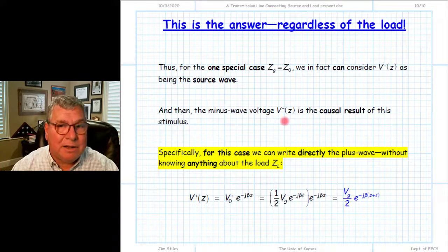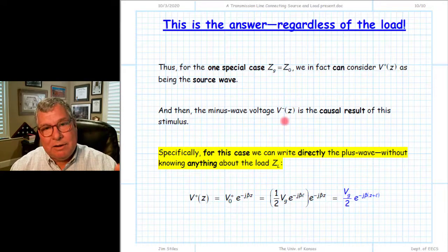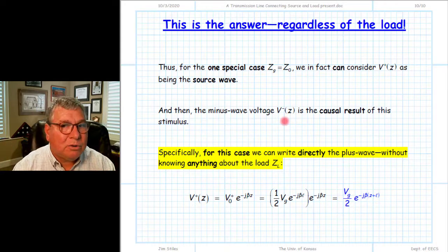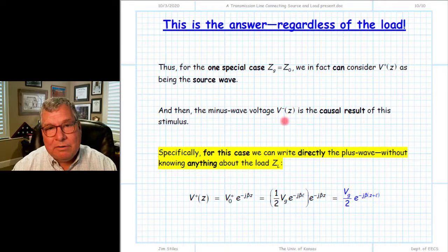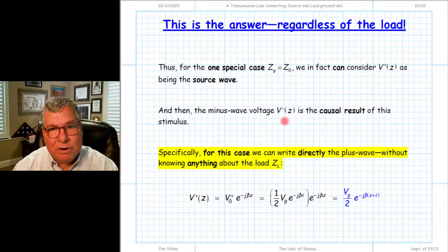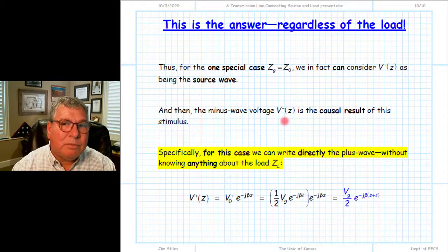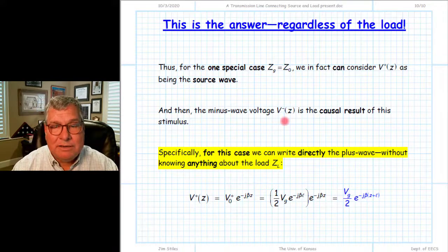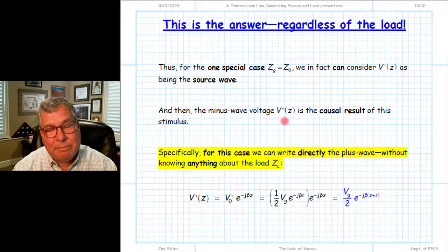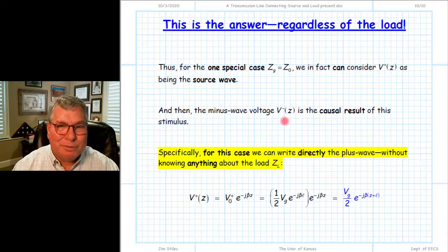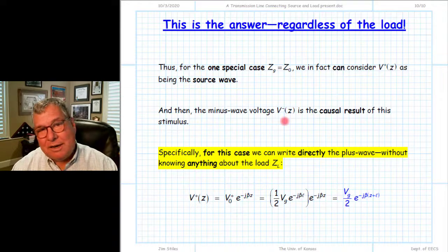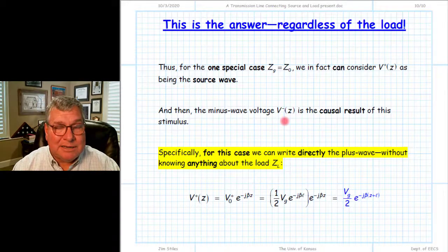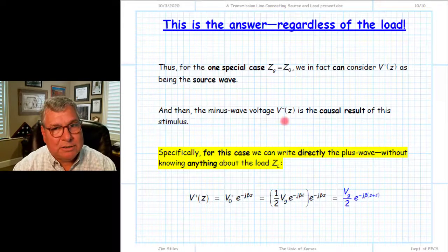If it's not, if it's something else, then we will get another reflection off the source, and a second time, a third time, a fourth time. We have a summation that would add together to find the total steady state result. All that math where we do the summation, the infamous summation in the case where we have multiple reflections, we do in ECS 723, but we're not going to do that in this class. Also in ECS 723, we can see that when we have a matched source, our infinite summations of multiple time around bounces and propagations reduce to a single simple term, one that is attributable to the matched source and the matched source alone.